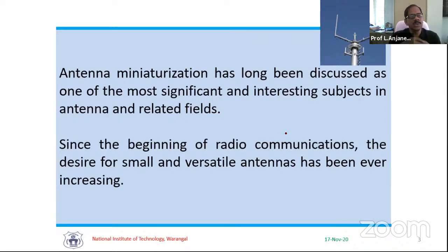professors or scholars who do research in the microwave and antennas field, generally their main focus is, compared to what other researchers have done, they want to improve it by some delta x in terms of various parameters. For an antenna, there are usually many parameters, like the beam widths in both the horizontal and vertical planes, the 3 dB impedance bandwidth, the VSWR value, the return loss, and cross polarization. And if it is circularly polarized, then we find the axial ratio bandwidth and axial ratio value. There are so many such antenna parameters.